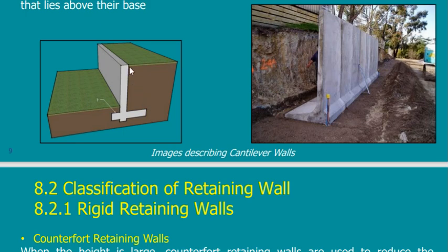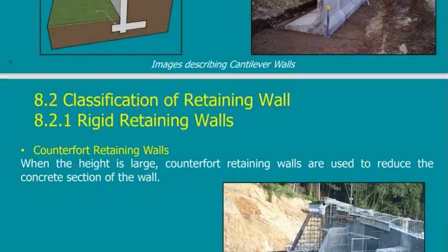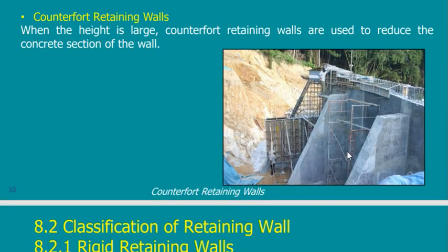The counterfort is always on the side where you are going to add your filling material. So I will put a counterfort here, and then after say 4 to 5 meters, I put another and another and another, so instead of having a cantilever slab, I will have a 3-sided slab. The slab will be carried in one direction on this counterfort, and in the other direction on this counterfort, and of course connected from the bottom. So it is only free to move from the top.